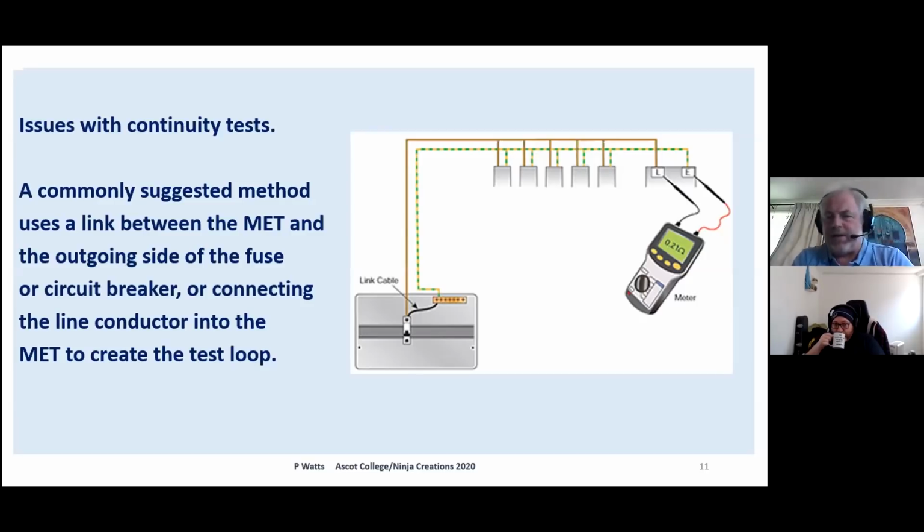Right, not my favourite idea, and I've actually had this on a brand new mobile unit, which you know about, because I told you about it. Brand new mobile unit that came in, all tested, all certified, all the paperwork and everything, and they'd left the link between the CPC and the earth. And we plugged it in, and there was an almighty great big bang. And we thought it was our circuit, and we reset it, and back went bang again, opened up the board.